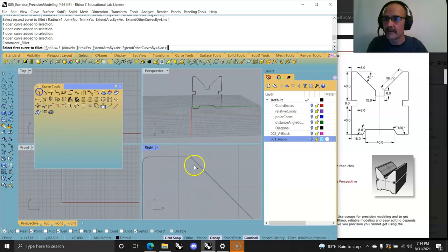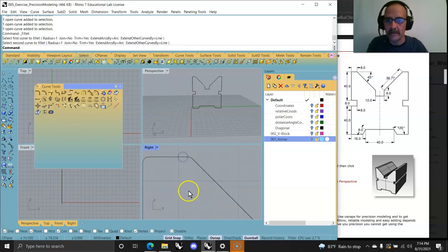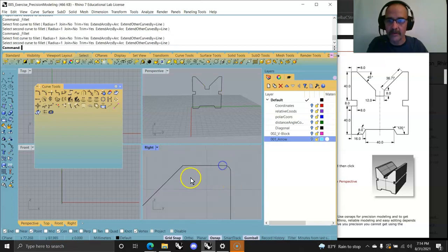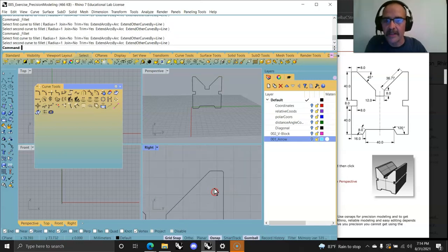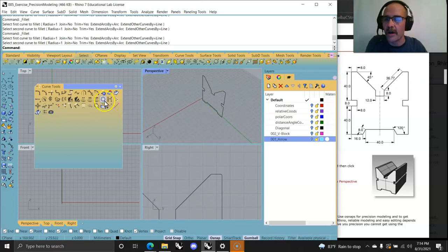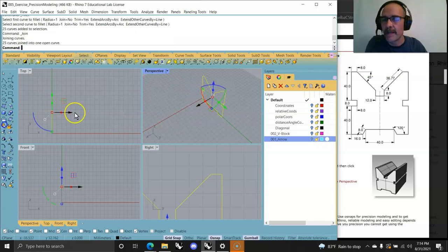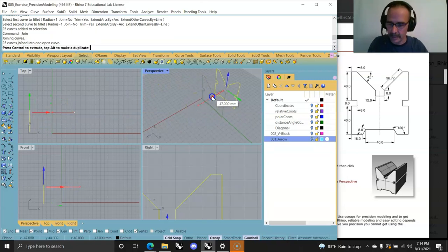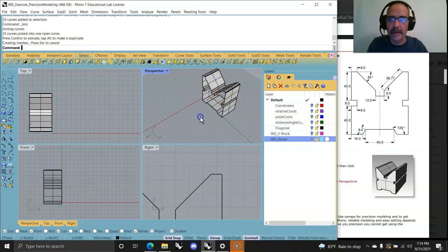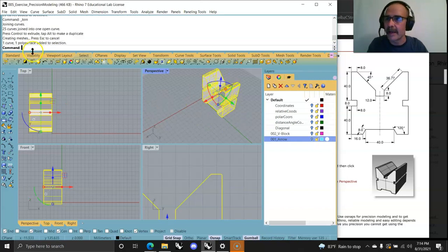Let's hit my fillet command first, not just click it. There we go. I got a nice little soft fillet there. And I might do the same up on this corner. Right click for the command to start, fillet, right click for this command copy, and we've done another light fillet. And that's just going to make a nice smoother top when I exit that. But before I extrude, make sure I join it back together, and we'll push that back in a little ways, Control Alt, and we've got a nice little one that I can go back in and cap.